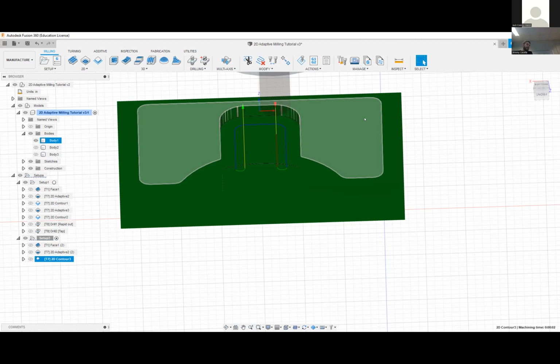Because they don't have to come back and say that this cannot be made, and then someone's going to send back the part and say, oh, we're not going to make this, or they're going to quote you like $1 million when it really costs $100,000 or something like that. So I think that's my big tip: the more you learn about manufacturing, you don't have to learn all the details of how to do all this. But for instance, you learned today that your corner size is really going to define your tool size. So the smaller I make a corner, the more difficult things have to be. I can't machine a sharp 90-degree corner on the inside, stuff like that.